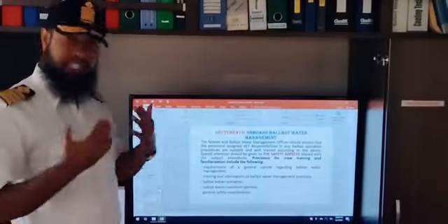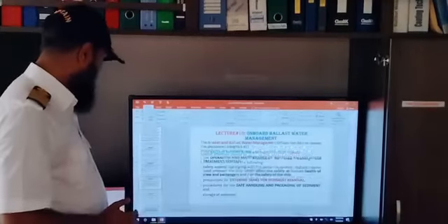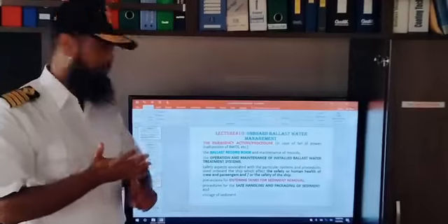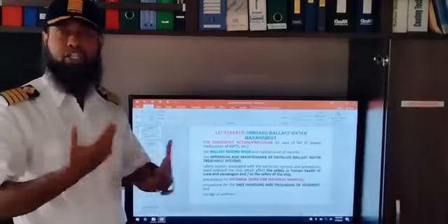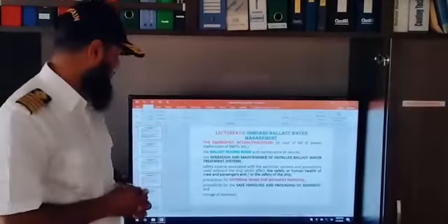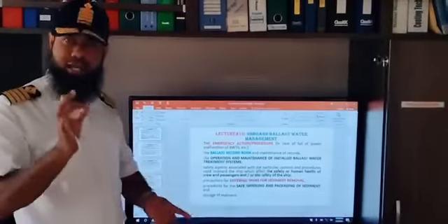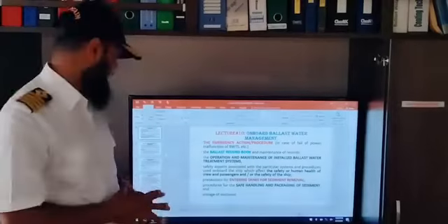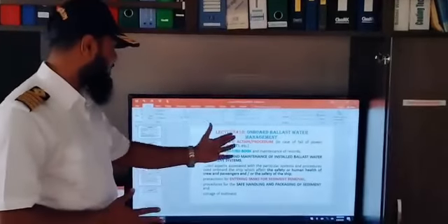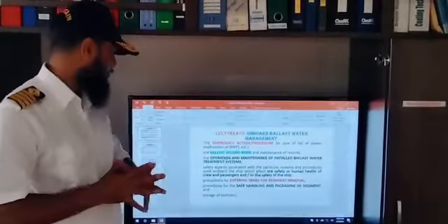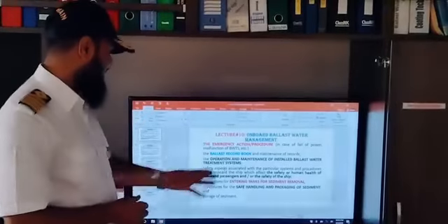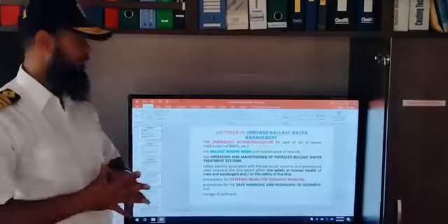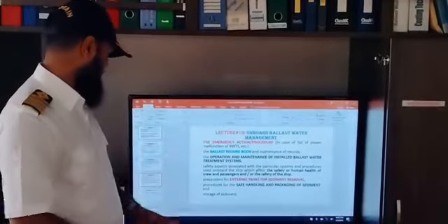And more things about the safety of the vessel. We have to ensure the emergency action or procedure in case of power failure or malfunctioning of the ballast water treatment system. The ballast water record book is to be updated and records maintained. And the operation and maintenance of the installed ballast water treatment system, and how to maintain, during the operation, the safety of the personnel and the safety of the overall ship.